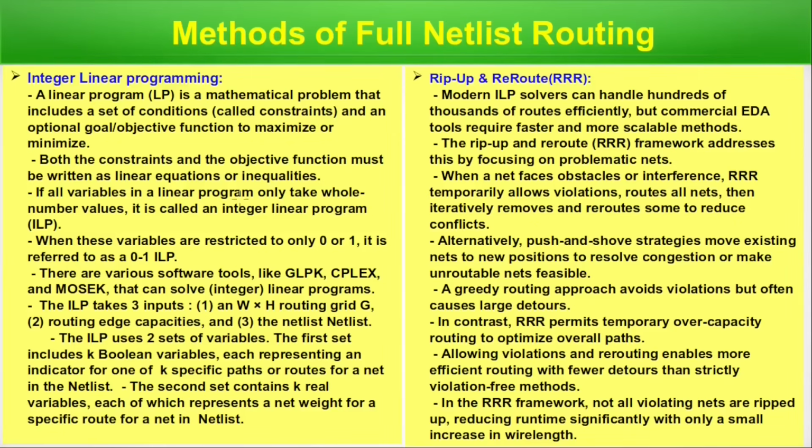There are various software tools that can solve integer linear programs. Now rip-up and reroute. Modern ILP solvers can handle hundreds of thousands of routes efficiently, but commercial EDA tools require faster and more scalable methods. The rip-up and reroute framework addresses these by focusing on problematic nets.